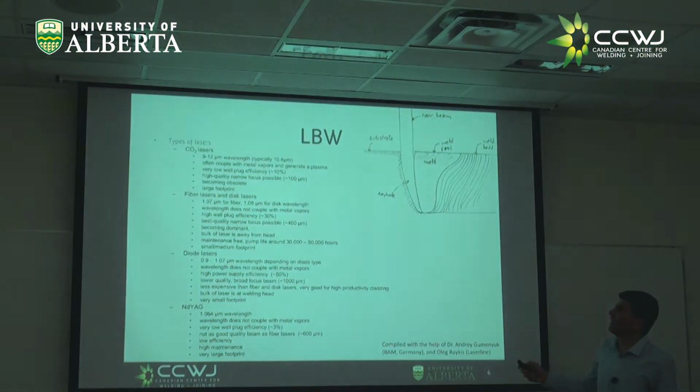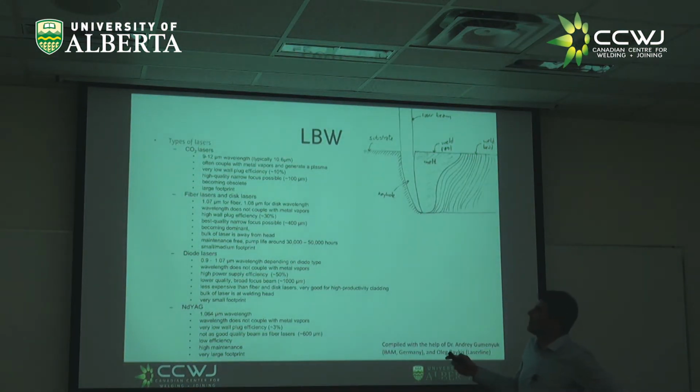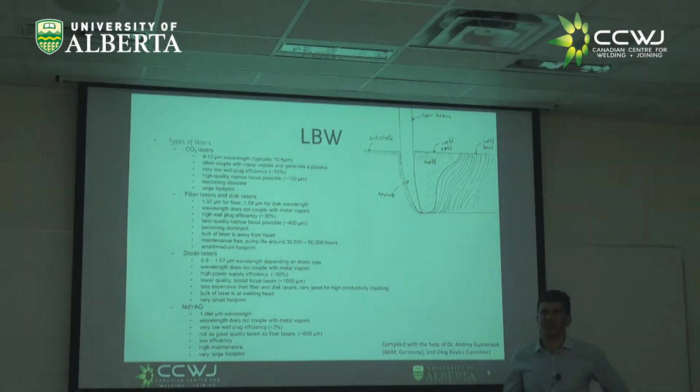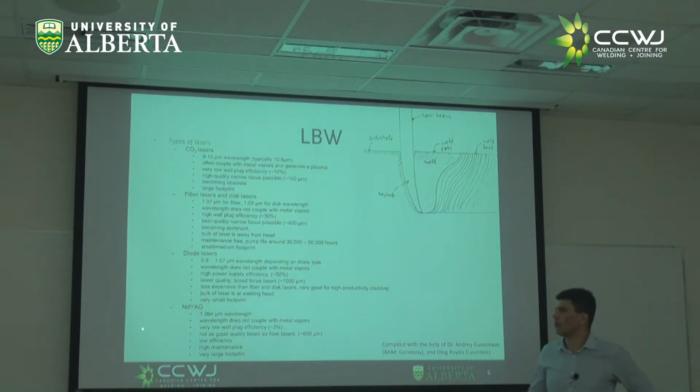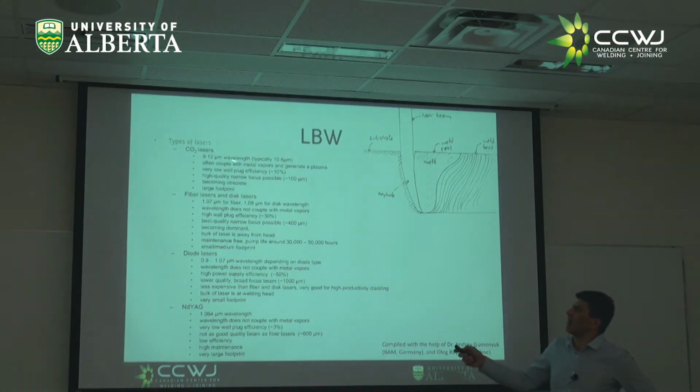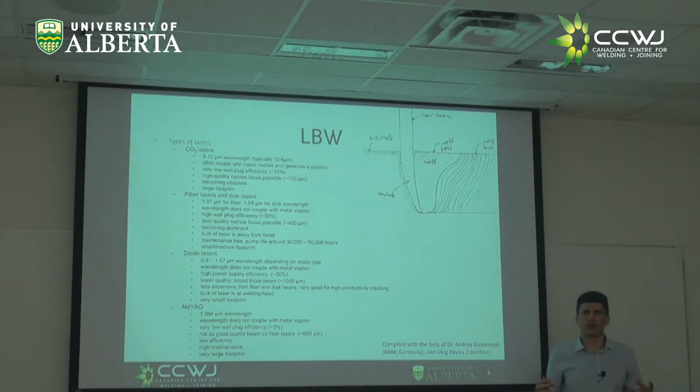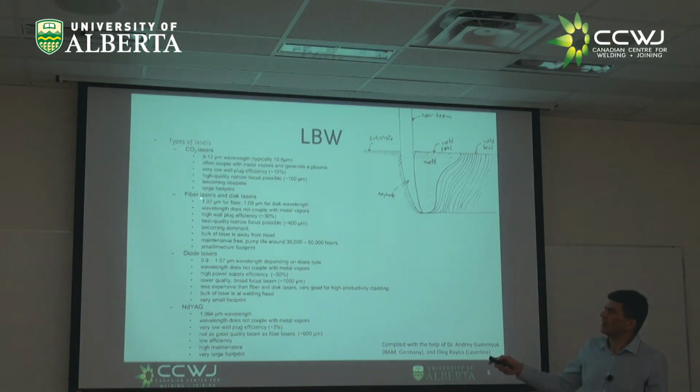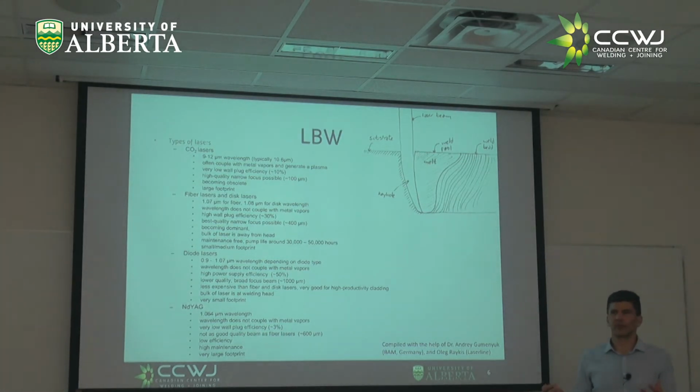Types of lasers, right? They were talking about this neodymium YAG. These are used for low powers now. They're not very popular for welding. CO2 lasers used to be popular. Those were lasers of enormous power, right? But what is now coming quite strong are these diode lasers, these semiconductor lasers.